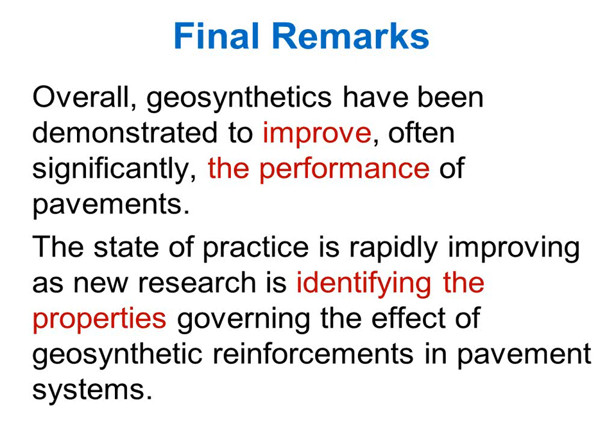For the transparent soil, do you include the oil or fluid during the test to make it transparent? Yes. So that's an advantage of us testing this pullout system in a vertical direction. The soil matrix is under confinement, but it's very granular, so we do not generate pore water pressures, but we do have the oil in order to observe.